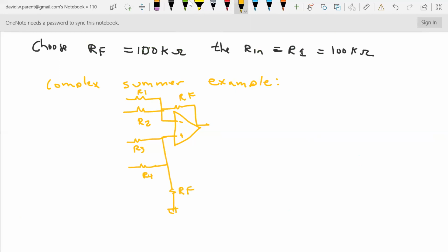Right? And that there's a voltage division going on here, and then you multiply it by the total gain up here. Okay. But you're going to need to be able to design it, and those voltage division equations are actually a bit tough. So what I just want to say is, the sum of the k's on the positive need to equal the sum of the k's on the negative, then